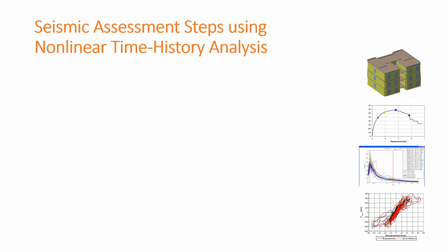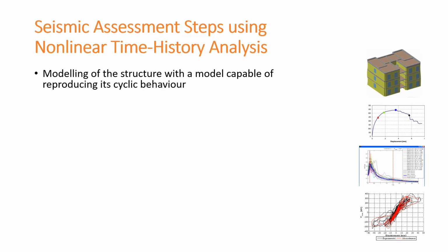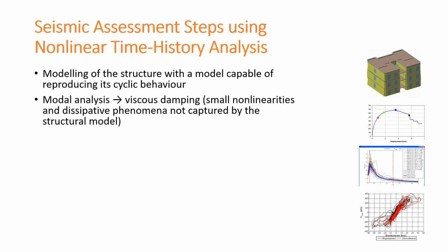So we can summarize the steps that are required for the seismic assessment by means of nonlinear time history analysis. And these steps are the modeling of the structure with a model capable of reproducing its cyclic behavior, possibly with reasonable times of analysis, let's say minutes, not hours.